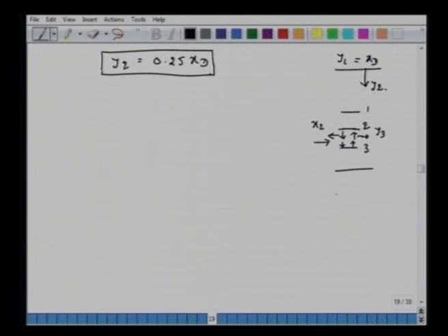So in this plate between 2 and 3, if you recall, we established Q line. What was the Q line? Q line, we had energy balance. Whatever energy is brought in here, we had energy balance between the two streams of vapor here and for the liquids here. All right. So now what we are trying to do here is extend this operating line for the stage just underneath 2. So we started from xt, then we got y2. Now we will write down the expression for y3 and x2.